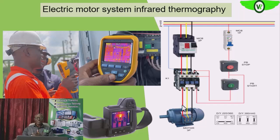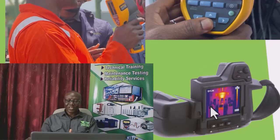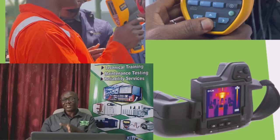So any deviation from what is normal, as we view on the thermogram, as you can see here, you can attest to the fact that these are not the same. There's something happening here. If there's any deviation, that will tell us that something is building, and it is definitely because of a resistance buildup around that area.